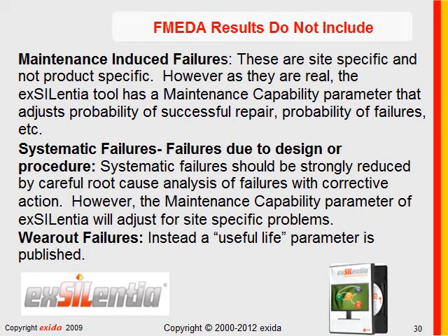Now, I will say that the exSILentia tool has a maintenance capability parameter that adjusts many parameters, including probability of repair and probability of failure, according to maintenance capability. And that is, in my view, an excellent way to deal with site-specific variations in PFD data.